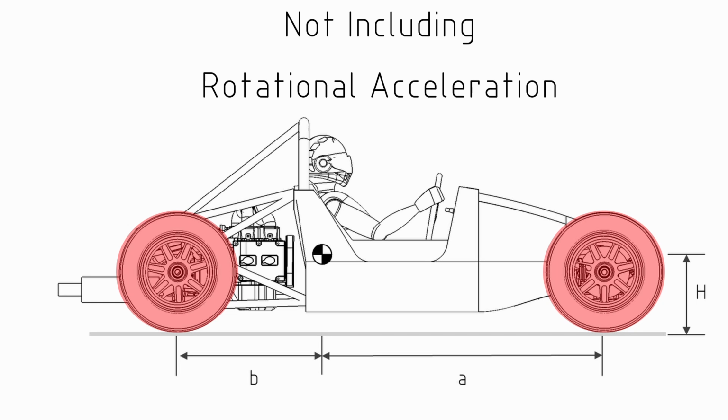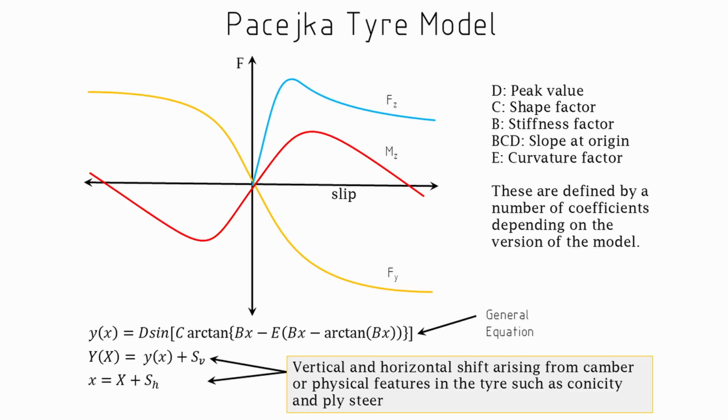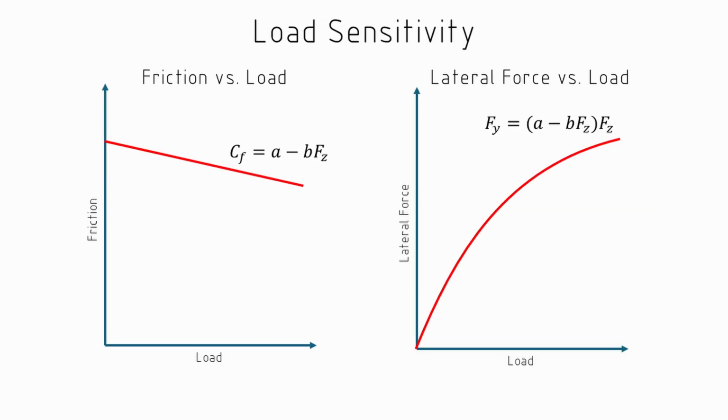We have a simple tyre model. We're not including load-dependent friction, and we're not using a slip model for the tyre. Now this is something that can be somewhat accounted for by using a slightly lower than expected friction coefficient. And this is something I used existing test data in order to sort of calibrate this simulation based on real life performance of a Lotus Elise.